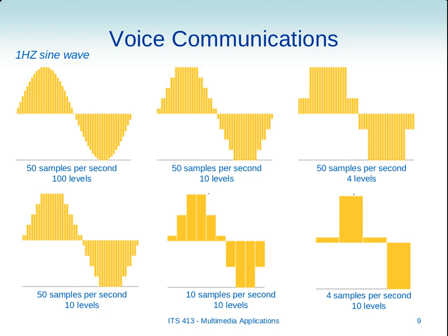In the second case, we have just 10 levels. We would need how many bits? 4 bits. With 10 levels, 3 bits can give us 8 levels. 4 bits are needed, therefore, to give us 10 levels. 4 bits give us, in fact, 16 different levels, but to get 10 levels, that is, to represent the decimal numbers 0 to 9, you need at least 4 bits. And in the last case, 4 levels, we need just 2 bits.